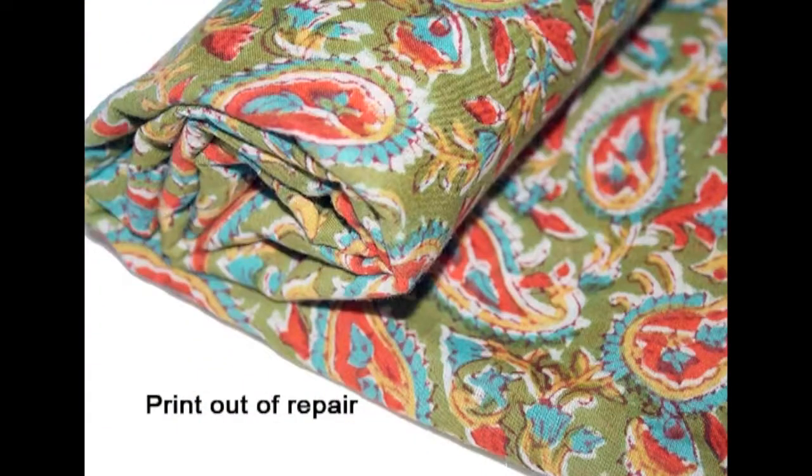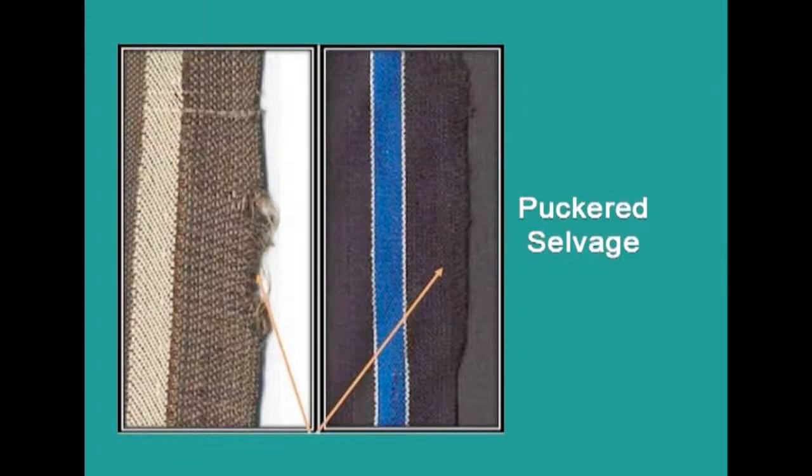And print out of repair, that means caused by print rollers not being synchronized properly. This results in various colors of the design not being printed in the proper position. And puckered selvages are usually caused by the selvage being stretched in finishing or by uneven wetting out in the sanforization process, and this is definitely considered as a major defect.